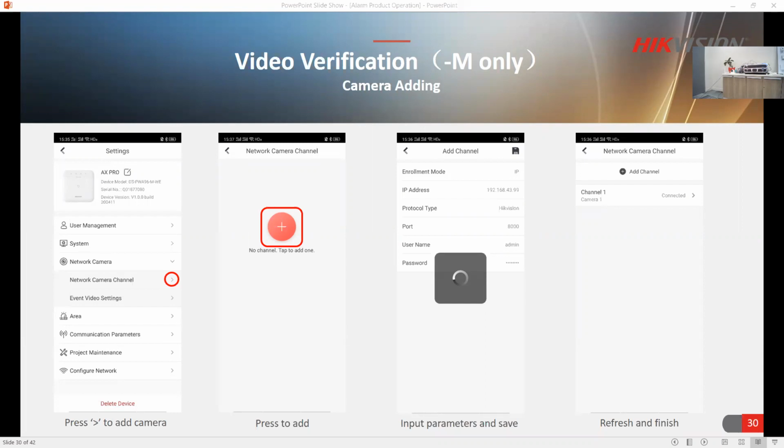Let me just stop moving so that all the lights don't see me. Right. Okay, it's telling me my cellular is lost. Okay, so now my system is armed. If everybody can hear me, I'm going to cross the line, and I've already programmed that the line crossing needs to flash on the strobe light on the camera itself. But once it does that, it will go into alarm on the AX Pro.